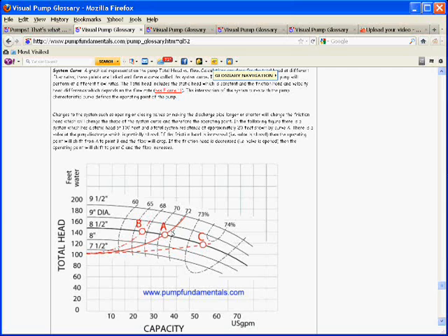Think about it, and next time you do some calculations, just plot that on the manufacturer's curve, and this way, if anybody asks you what happens to this pump and this system if we're running at a lower flow, bang, bang, you got the answer.